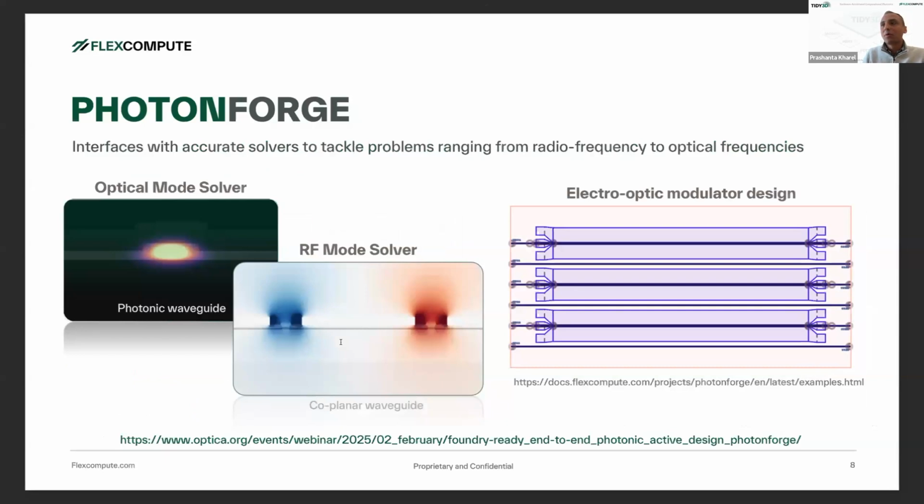Another big part that we're focusing on is also trying to bridge that gap between photonic simulation and also RF simulations. Especially, one thing I realized is a lot of people from photonics background don't really end up doing a lot of RF simulations, but RF simulations are pretty critical if you want to build a working device. And so we are integrating both the optical and RF solvers through our platform. We have a lot of example notebooks to show you how to design, for instance, a high-speed Mach Zehnder modulator in thin film lithium niobate platform.